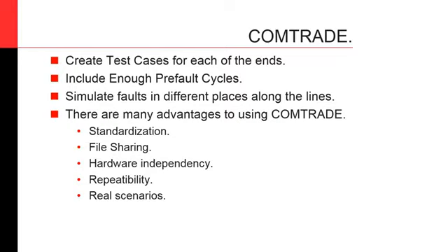It's a standard that allows a common representation of oscillography coming from any kind of oscillographic recorder in the system. And since it is a standard, it allows people to see it in standard tools, some of them free on the internet. You can find them, or some are built into the configuration tools used to configure relays.